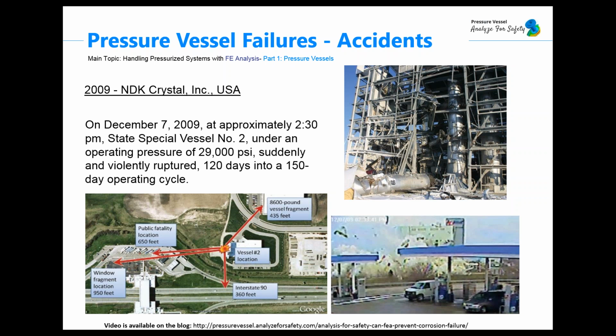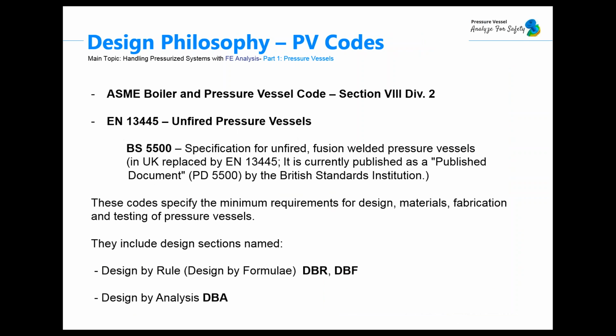And those accidents demonstrate the potential danger of pressure vessels, and once again I will say the scale of consequences if they are not properly designed, constructed, operated, inspected, tested, and/or repaired. So the higher the operating pressure, and the larger the vessel, the more energy will be released in a rupture, and the worse will be the consequences. And it should be emphasized that the danger exists even if the vessel contents are not flammable, reactive, or explosive.